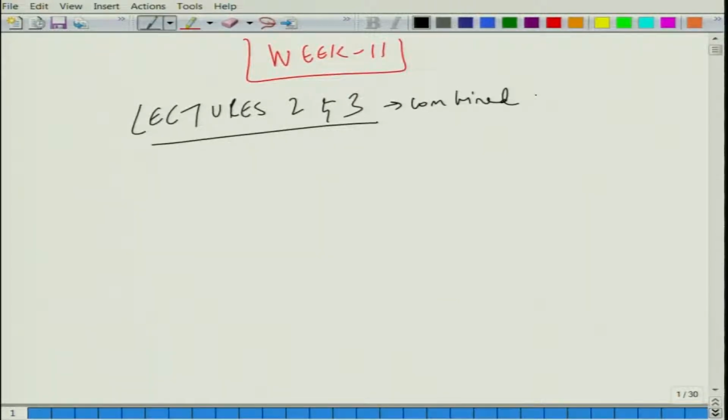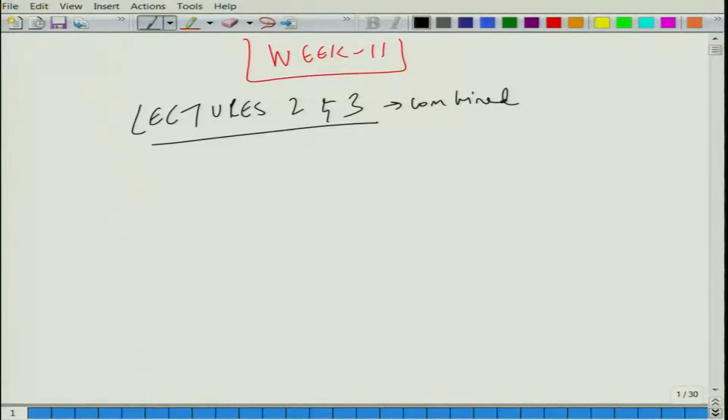So, what we are going to do exactly in this lecture is that we will present a proper theoretical formulation of how to characterize different single inlet and single outlet rectangular chamber mufflers as well as circular cylindrical mufflers with arbitrary location of ports. Although this formulation, like I mentioned in the last class, can be used to analyze systems with multiple ports, I mean more than 2 ports, like single inlet and double outlet or single inlet and triple outlet or 2 inlets and 1 outlet and different combinations, but we will restrict our discussion to single inlet and single outlet system or SISO system. So, we essentially have a 2 port system, a 2 port rectangular chamber or a circular cylindrical chamber.